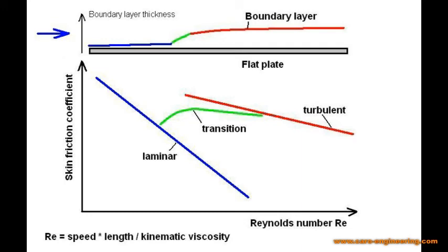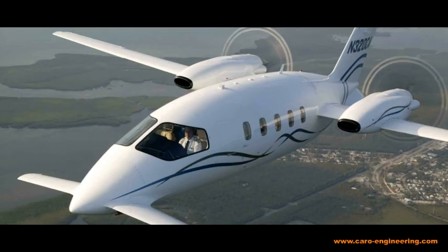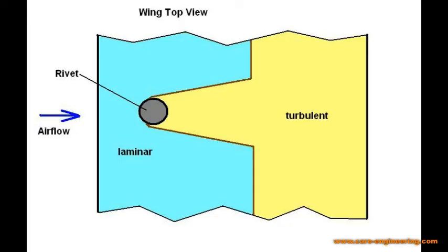For the lowest drag, the boundary layer needs to stay laminar as long as possible to minimize the skin friction drag. The laminar boundary layer is quite stable until the thickest part of the object is reached. It is hard to keep it laminar much beyond that. For that reason, the thickest section of bodies and airfoils is shifted aft as far as practical, where low drag is important, during the design stage.